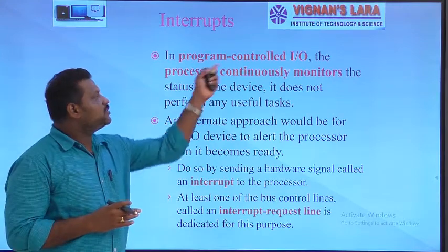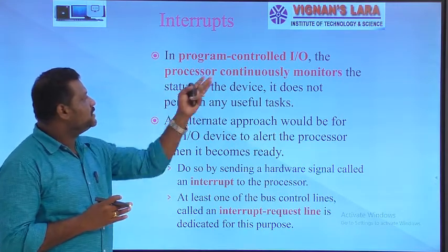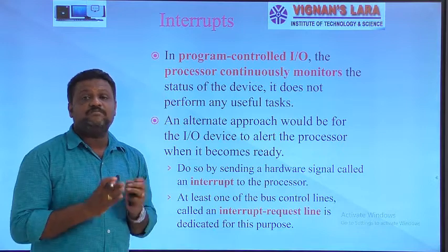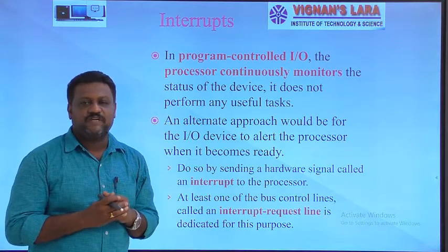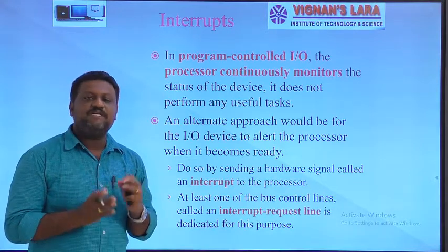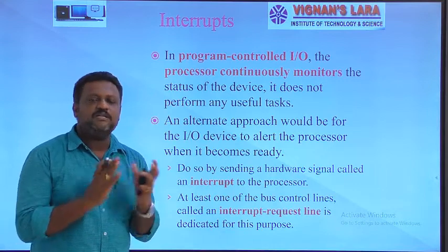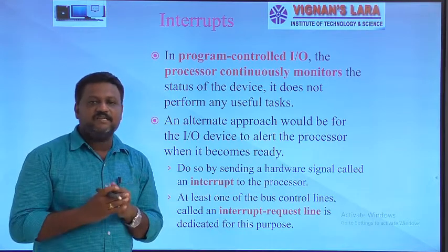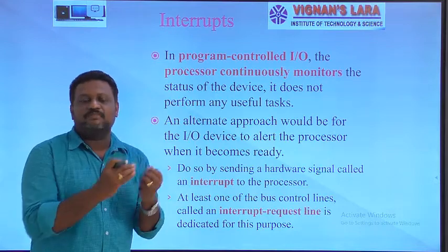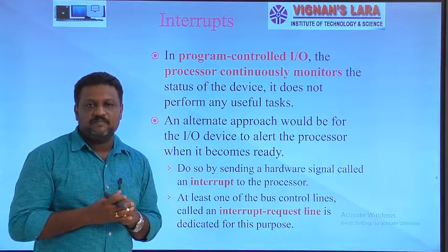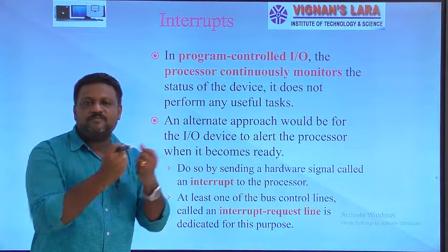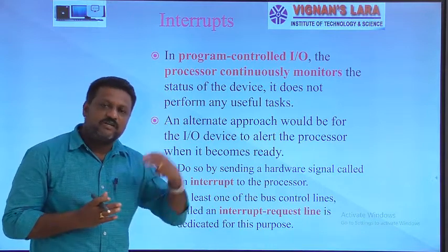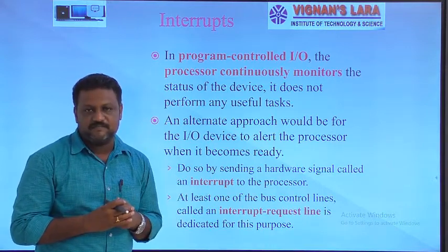So in programmed controlled I/O, the processor continuously monitors the status of the I/O device, whether the device is ready or not. Why? Because if the device is ready, the CPU can communicate with it, either to receive something from the device or to transfer something to it.